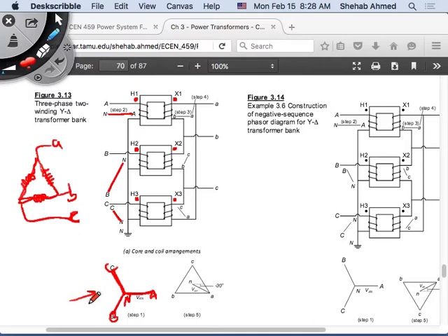So what do we get on the secondary side? To do that, we do the following. Okay, phase B, the B terminal is away from the dot. But before I do that, do we agree that the voltages in the primary and the secondary will be in phase as long as the windings are on the same core, and the dots are in this fashion together? If the dot is flipped, then the voltages are also flipped. If the dots are in this fashion, then the voltages are in phase.